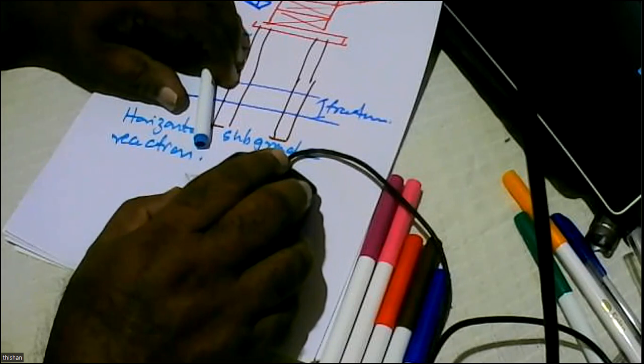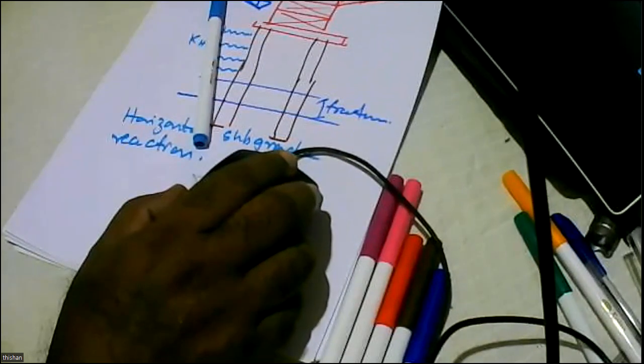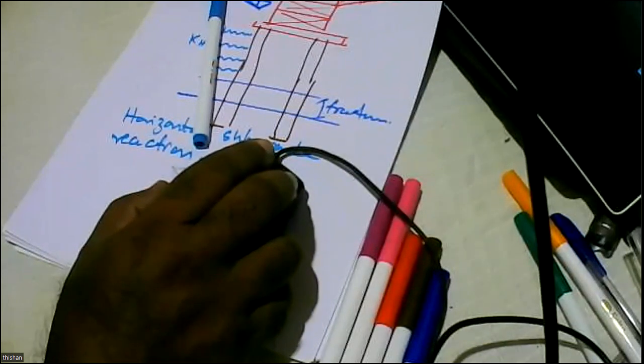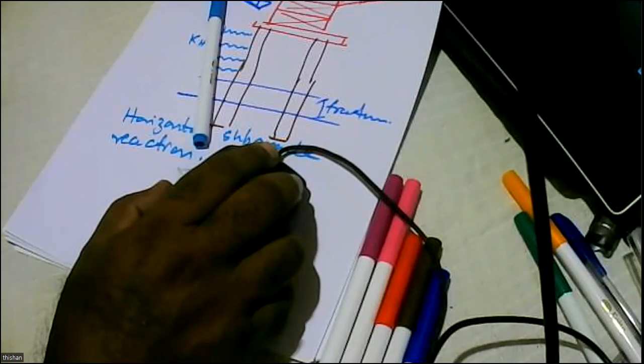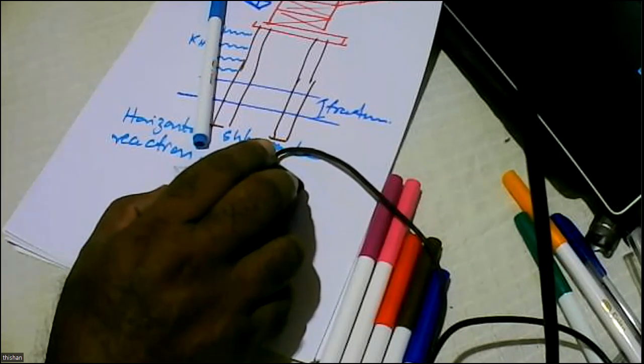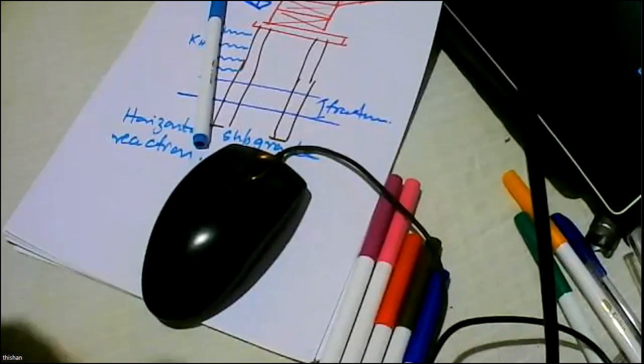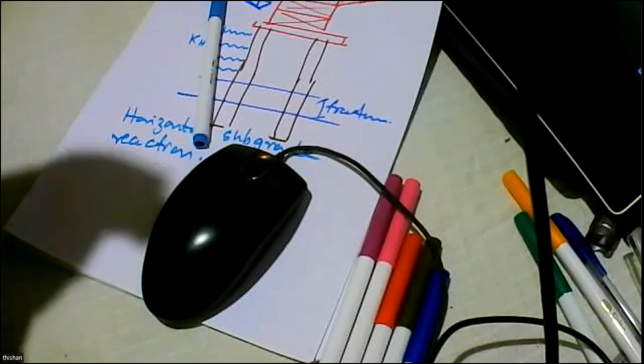Sometimes when you have clay soils, they may not be fully of laterite origin. So you might find they are really weak soils, like SPT less than 2, which means very bad soil. You might get SPT of 2 to 4, again pretty bad soil, but not the worst. But when you get SPT of 4 to 8 in clay soils, we generally say they are reasonably firm soils.